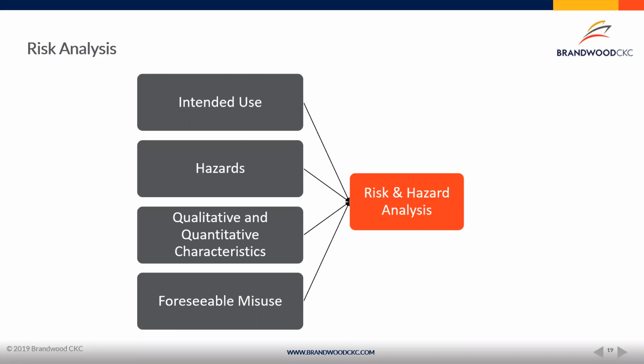You really have to focus on the fact that there are foreseeable misuses, and you need to do your risk analysis to include those. So even though your device might be meant to be used in a clinic by a person who has appropriate training, well, what if somebody isn't as trained? Or maybe somebody picks up the device for the first time and tries to get the result that is intended. Well, what are the foreseeable misuses? And around that could be usability issues.